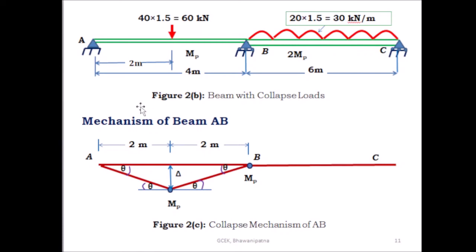Here also you have to go for two mechanisms. First mechanism for span AB and second mechanism for span BC. First start with the mechanism of span AB.